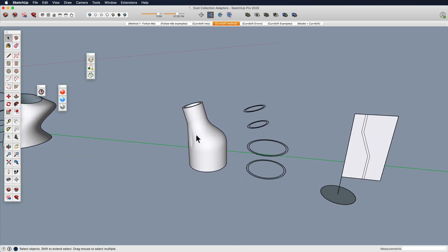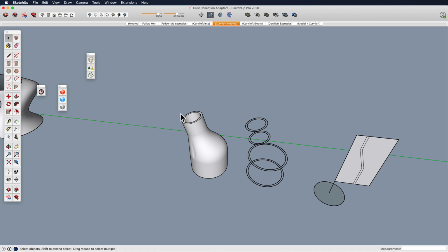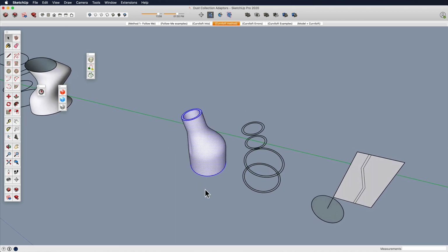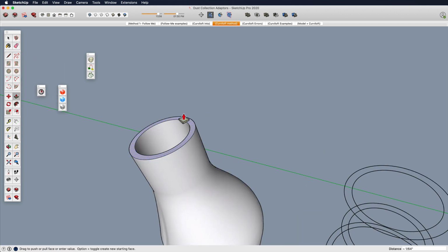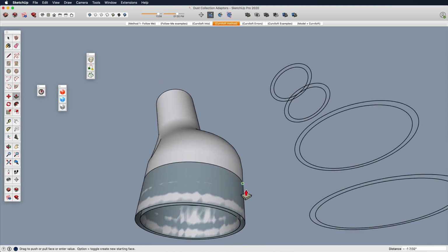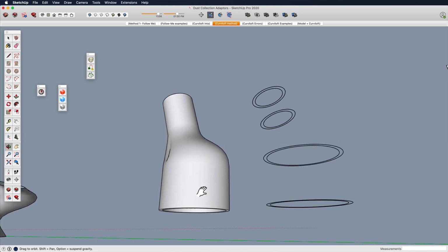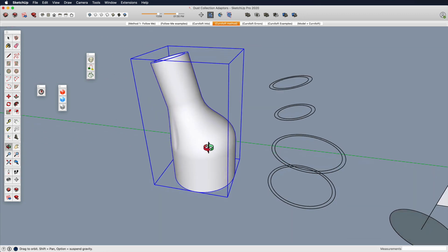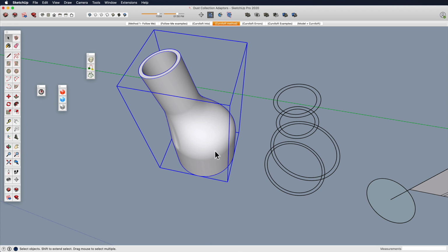There we go. Aside from that little thing, I would change it up a little bit, maybe change the spline, maybe change the spacing if that really bugged me. But there we go. Now we've got a dust collector, or dust hose adapter, that starts here and goes off at an angle. And if we needed to extend this out, because these were in line, we could extend this, extend this. So group it, export as STL, and send it to your 3D printer.